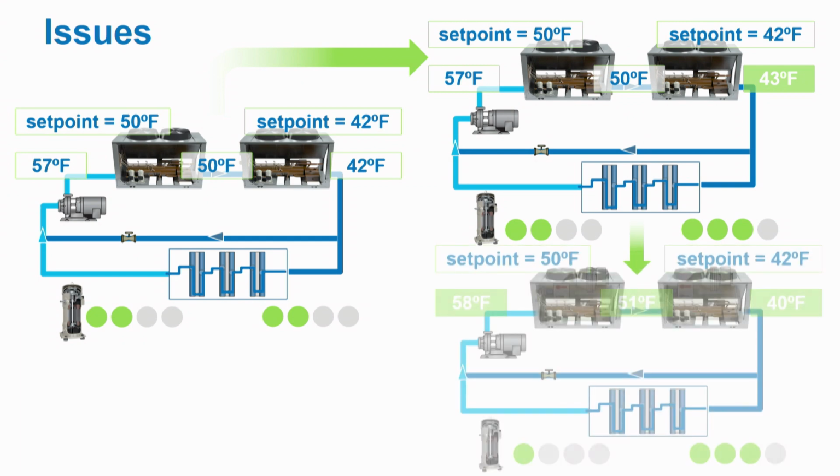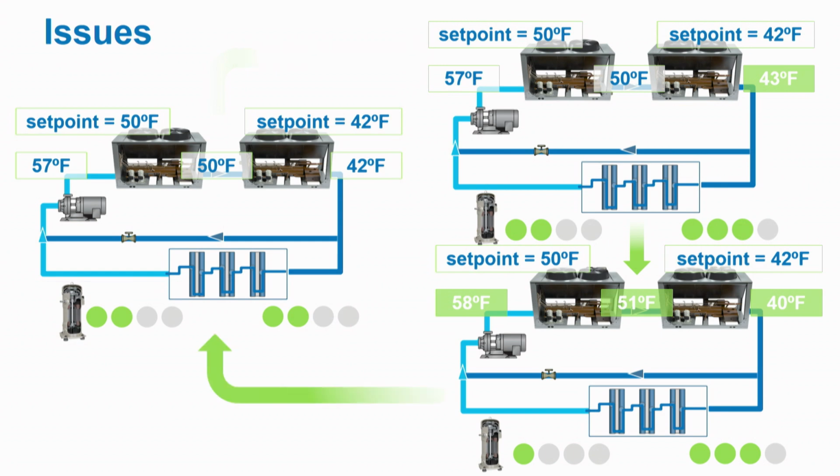This causes the return water temperature to the upstream chiller to drop, so the upstream chiller turns off one of the compressors. Now, the upstream leaving chilled water temperature rises. At some point, it rises far enough that the upstream chiller's second compressor comes on again. That decreases the temperature entering the downstream chiller, and with 3 compressors operating, its leaving temperature drops far enough, causing one of the downstream chiller's compressors to cycle off. Therefore, the upstream and downstream chiller hunt, with compressors on both chillers being turned on and off.